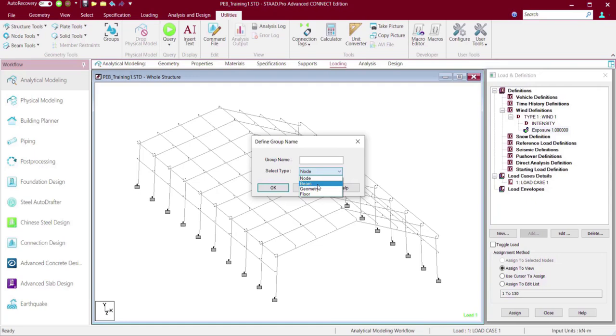First of all, these metal sheets are very thin. They have very insignificant stiffness compared to the main structural frame. So they don't contribute to significant stiffness. But yes, they have the purpose that they will transfer the loading to the supporting purlins, girts, and then the web sections. Sorry, the tapered sections.